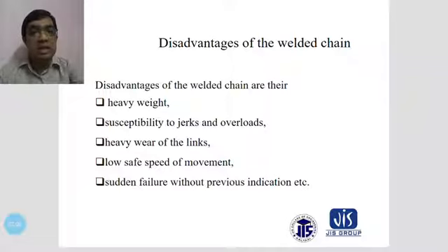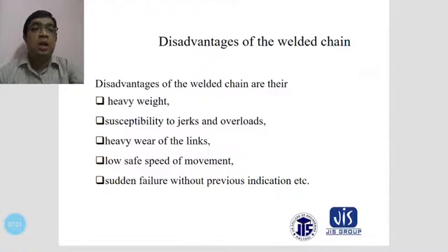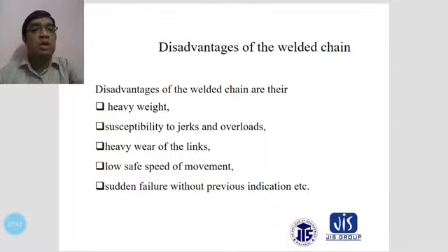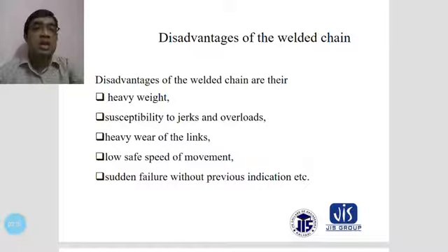Another thing is the low speed of movements. Basically, when a welded type chain is used, high speed cannot be given when moving materials from one place to another because of the heavy weight and the high wear. High speed is not maintained in this system, so a low speed is given. When high speed is required, this type of chain is not used in this system.